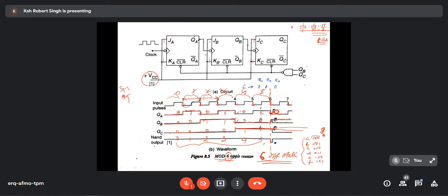Is it doing like that? No. But luckily, this flip flop is 0. But this flip flop, see, it is 1. This flip flop is 1. And again, this flip flop is also 1. These two flip flops, QB and QC, are going to create problem. But I want it to be 0.